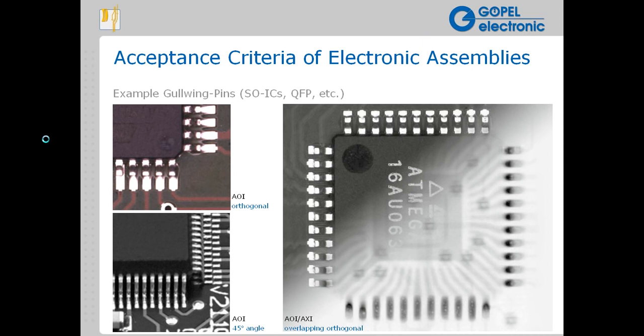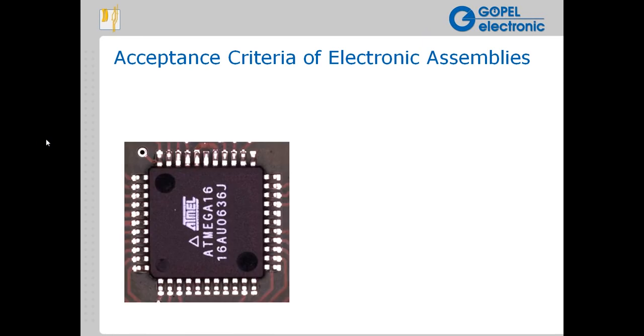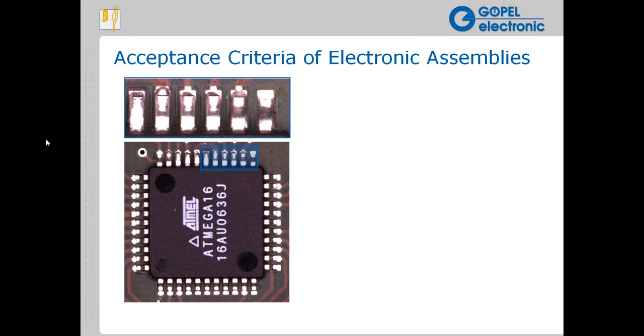Another example with a set of pins here that have another failure characteristic. Again, in AOI, you could see these pins, and I can tell you that our AOI system would certainly be able to detect failures in these particular pins. As you can see from the reflections, there are problematic solder joints here. But it's not always completely obvious what the nature of the problem is from the optical standpoint. However, if we look at this in X-ray, we can much more clearly see the characteristics of the solder joint. In the bottom left and right rows of pins, you can see very healthy solder joints. And then, of course, in the top, very poor solder joints. And again, if you compare that to the optical image, we could certainly detect those faults in our AOI system, but it's much more effective with the X-ray backing it up.